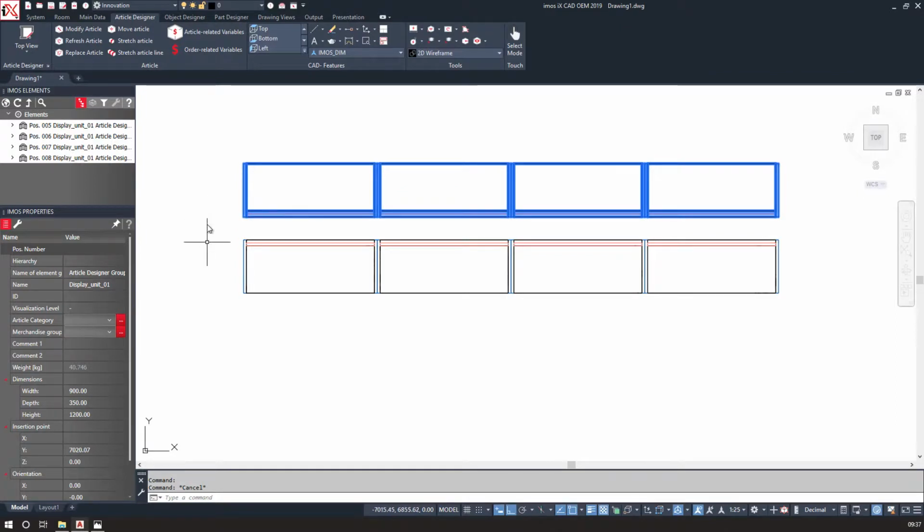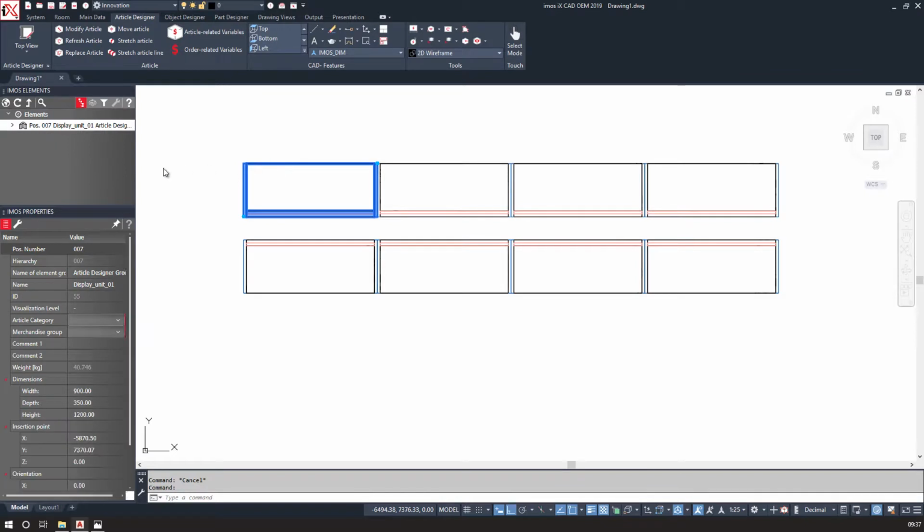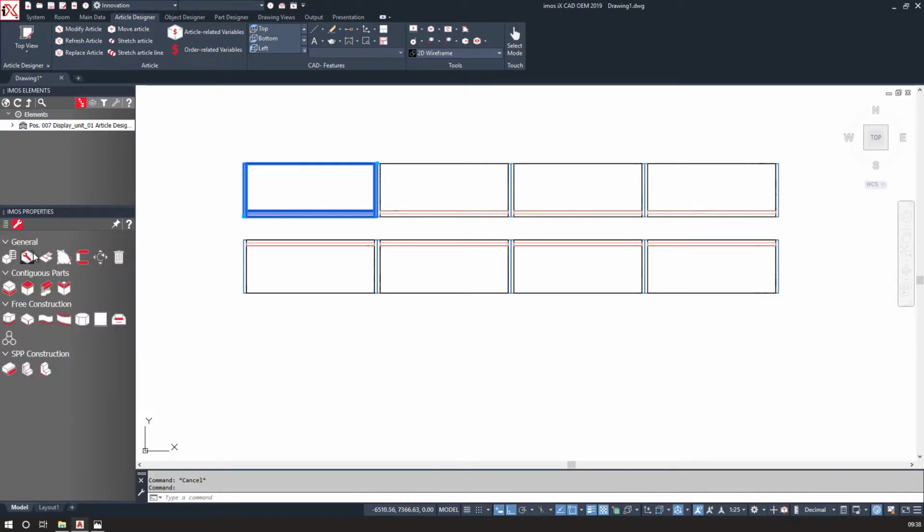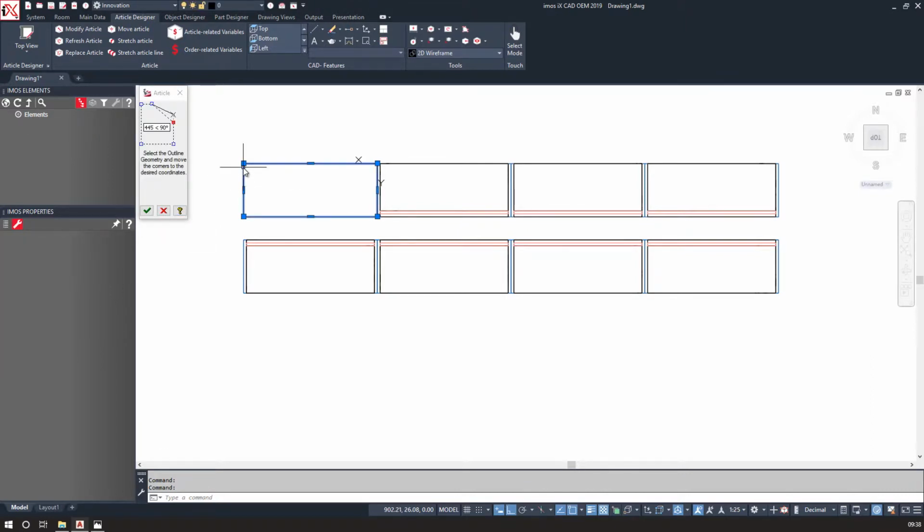The next step is to change the overall outline of the products. We can do this quite simply by selecting a product, go to the Modify tab, and choose this symbol here to modify the contour. This allows me to then pick the rectangle and change the overall shape. This can be done for all of the others to create an interesting break front. I'll do this now.